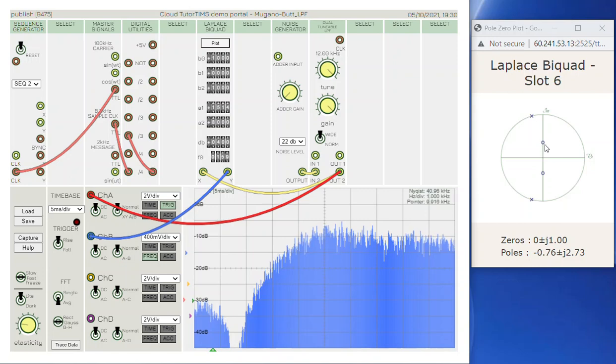As the frequency of interest moves up the axis, you can see we travel from DC into a notch, then up until a slightly peaky response, which relates to the poles. So poles are responsible for creating an amplification of the response, whereas zeros cause a nulling of the response.